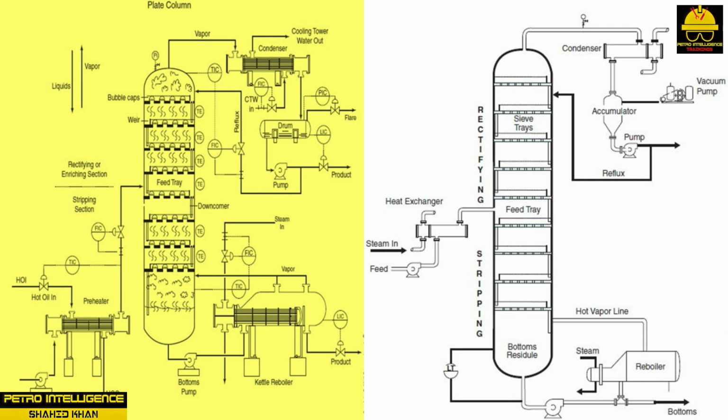As vapor flow leaves the column, it enters the overhead condenser, comes into contact with a much cooler environment, and condenses. The condensed liquid collects in an accumulator or drum. A pump takes suction off the accumulator and directs flow to two locations. The primary stream moves the distillate to the product tanks or on for further processing. The secondary stream is pumped back into the column as reflux.